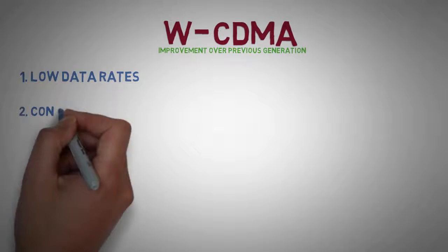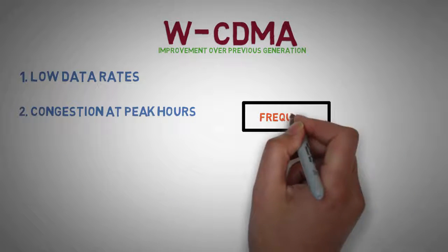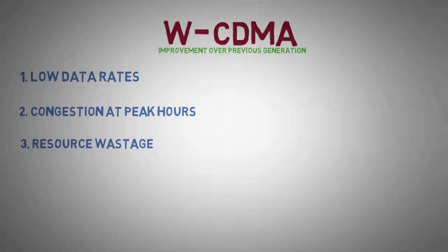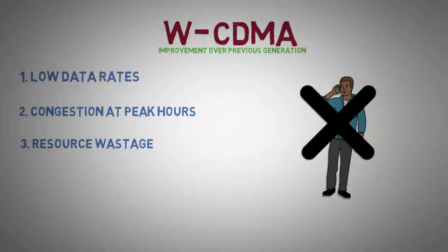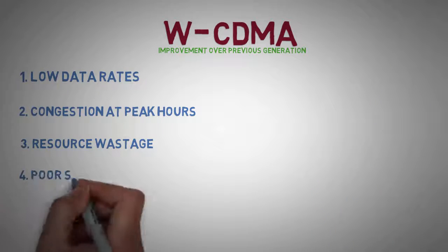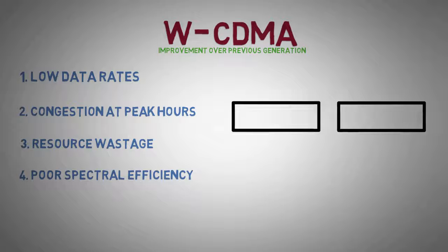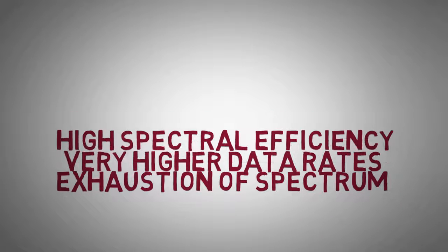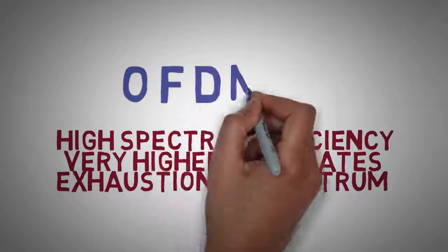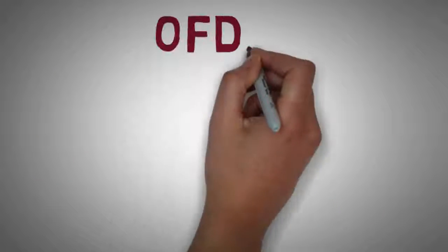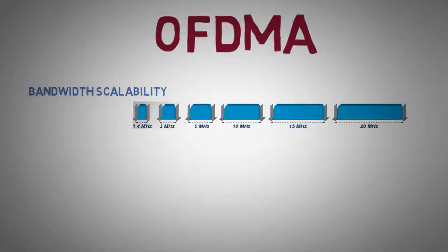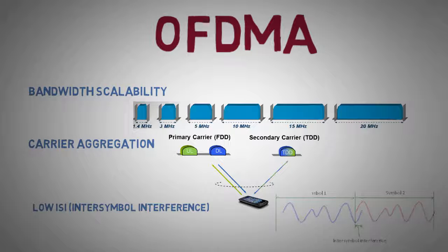Second, congestion at peak hours, as the frequency chunks and time slots were very limited. Third, resource wastage, resources remained idle when users were inactive. Fourth, poor spectral efficiency, due to guard bands and guard periods used to avoid interference. But, exhaustion of spectrum, need for even higher data rates, and spectral efficiency led us towards OFDMA. OFDMA comes with several advantages over WCDMA like bandwidth scalability, carrier aggregation, low intersymbol interference.